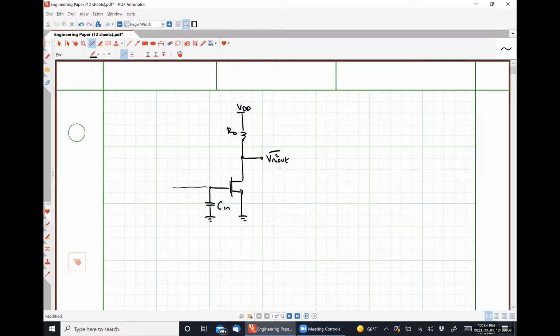Okay. So I'm going to apply the regular input network here. This would represent IN N, our input referred noise current. Here we're going to have VN N, our input referred noise voltage. And usually, we would apply our input signal here. And all of the input signals that we've been dealing with to this point have not had any associated source resistance.